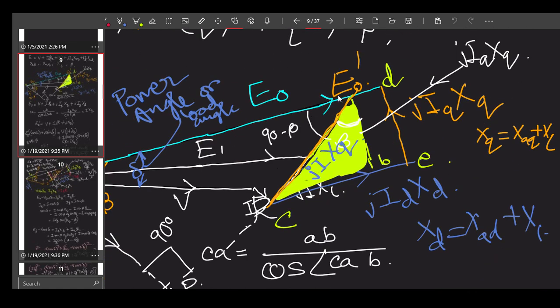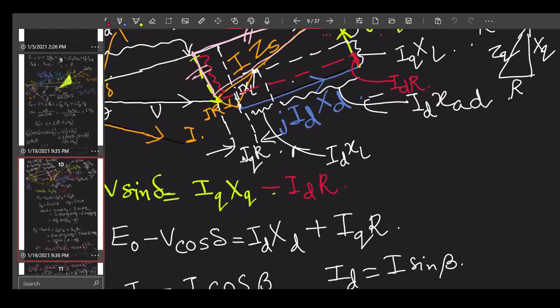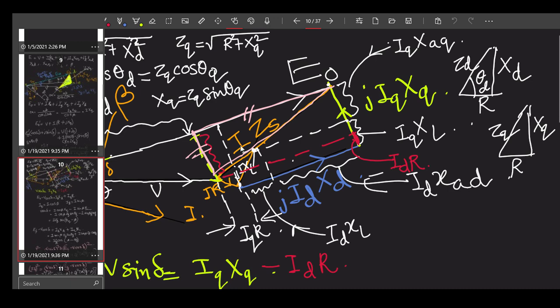If you are not trying to draw xd and xq, rather you keep E dash, then after drawing E dash you do not try to find E dot or E dot dash from this E by adding some vector, then perhaps you can construct the phasor diagram without explicit information regarding xd and xq, right? Like what I am trying to say once again,